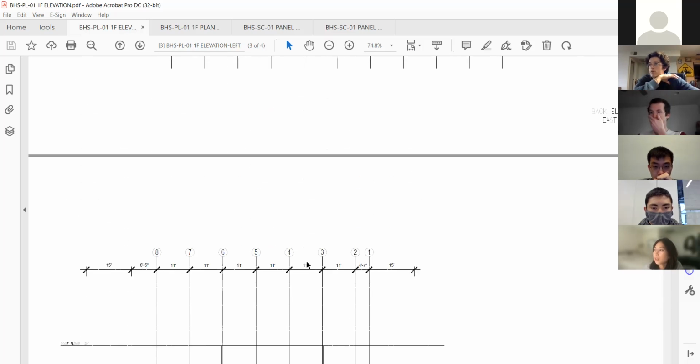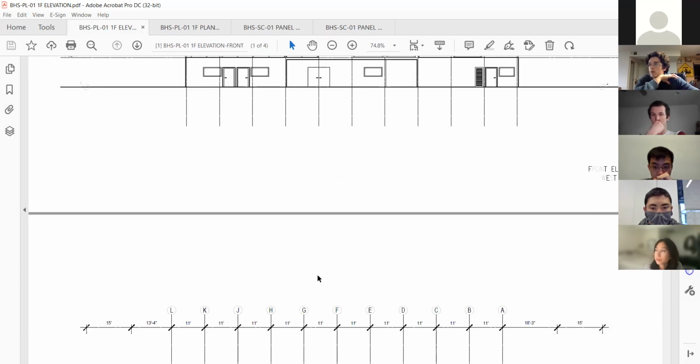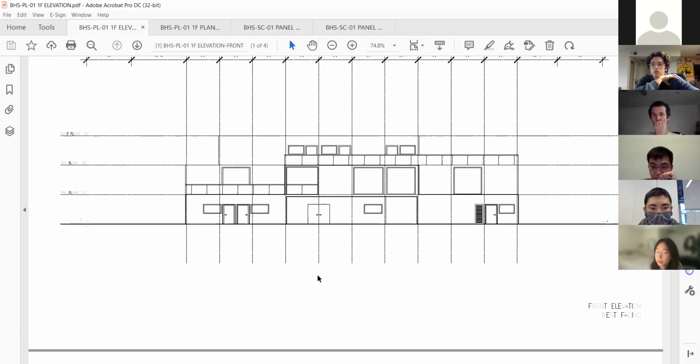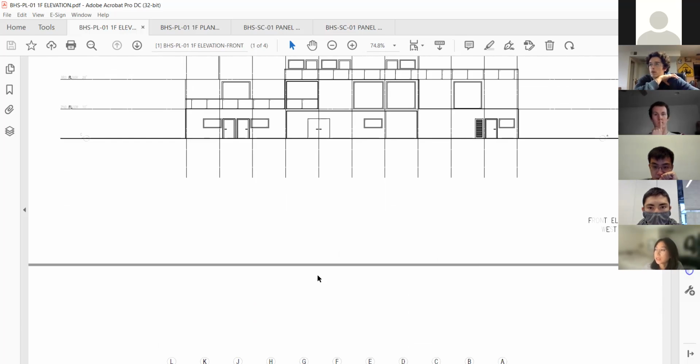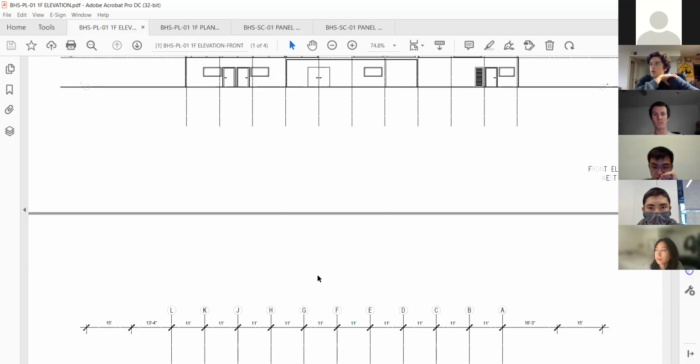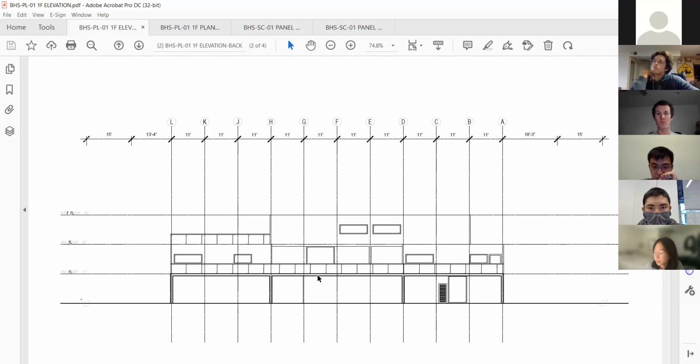Thanks. And also, I think for the roof slope, it's 1/4 inch for every 12 inches. Okay, it's actually not that steep. It's almost like a flat roof. The slope is really not as steep as what you have shown right there. So 1/4 inch. Okay.